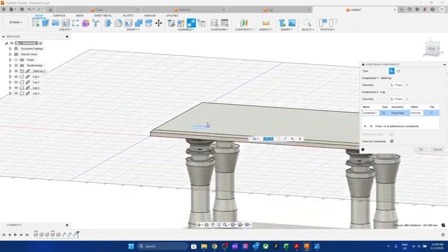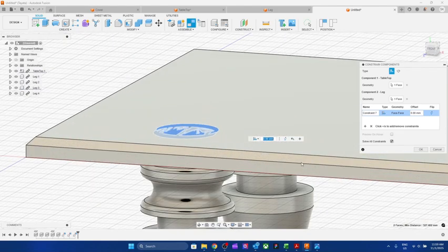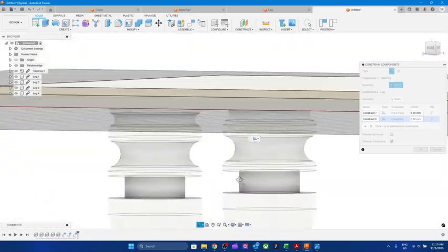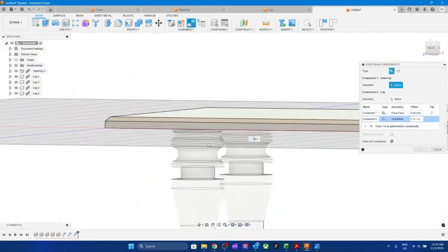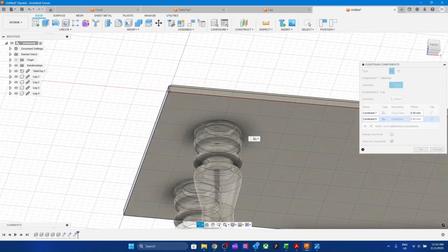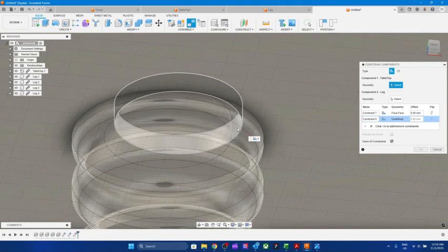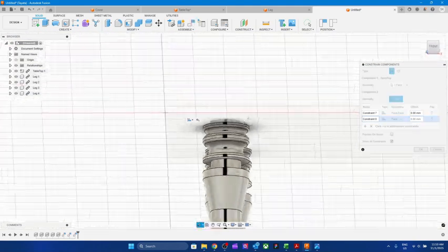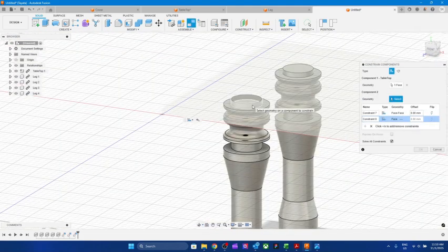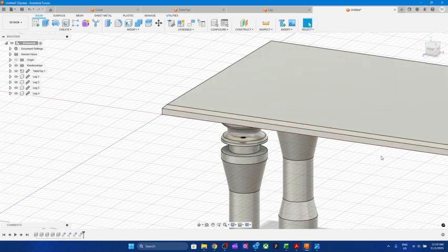But as you can see, look, it's not aligned, yes, because 2 diameters are not mating. So click OK, add one more dimension or constraint. So this is the internal. If you can't focus, you can simply zoom in and then select the top and click OK.